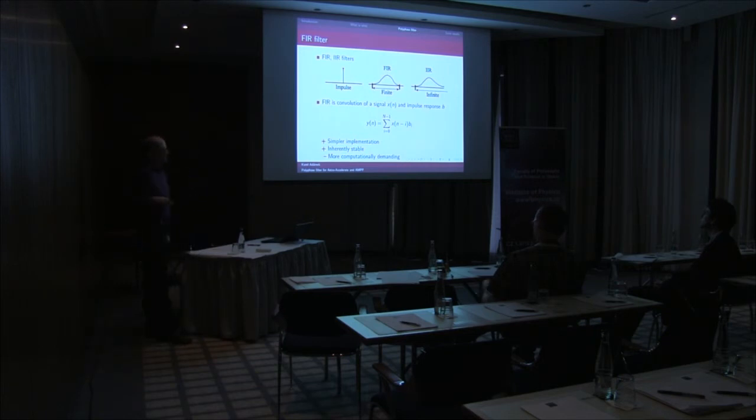And I forgot to say what a polyphase filter is. A polyphase filter is basically applying a FIR filter on n number of channels, where n is the order of your DFT transformation, which basically tells you how precise your frequency scale is. So more n means more precise frequency measurements. Also, another good thing is it is simpler to implement, but it's more computationally demanding.